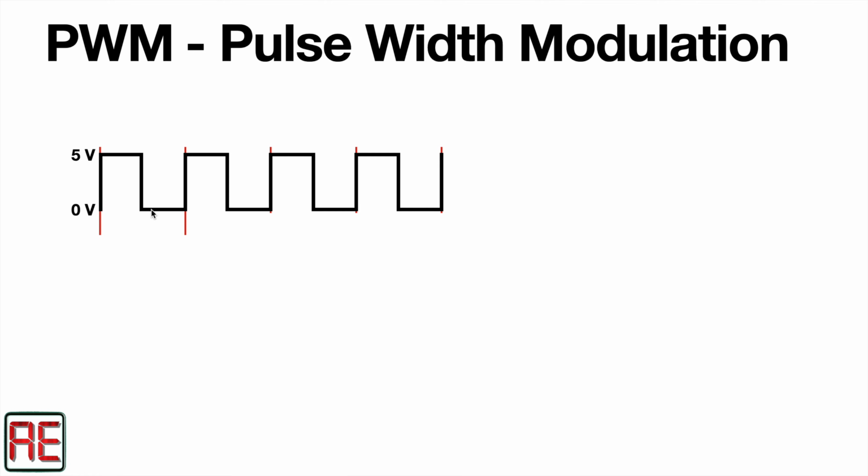This pulse train is periodic, with a period that we are going to call as T. On the PWM modulation, we control the pulse width by defining the percentage of the period in which the pulse is at 5 volts. This percentage is called duty cycle.